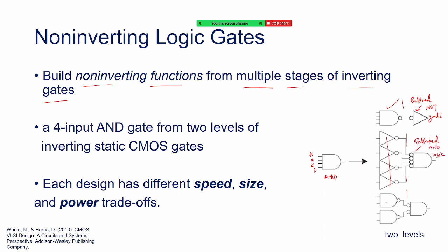Okay, and then is it an AND gate or should it be an OR gate? Which one? As per De Morgan's law, I think it should be an OR gate. Why and how? I saw in your slide that when we are using a bubble, it was converting from AND to OR. Yeah, you can verify that operation also, but these are the ways of implementing those functions. And the third case is to just split the 4 inputs and then use such logic.